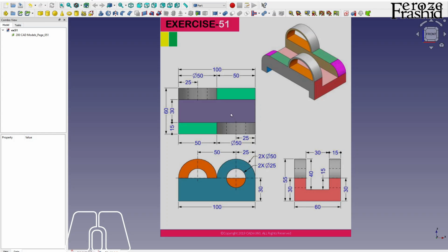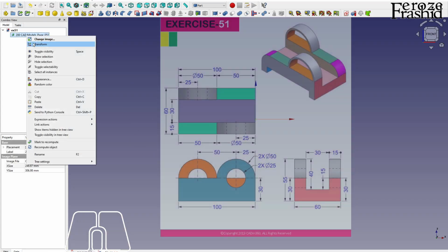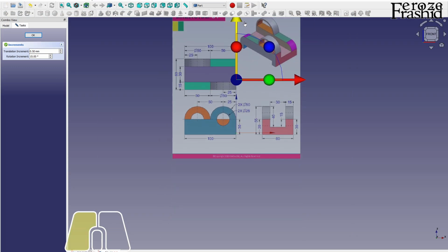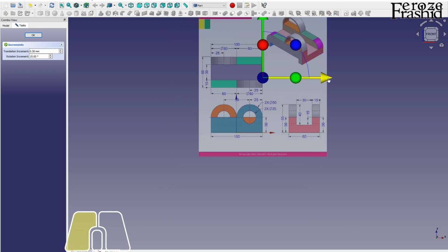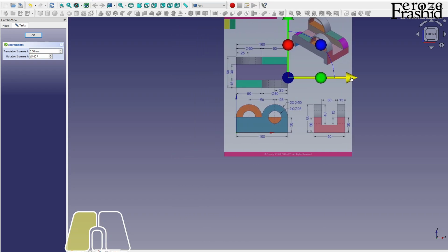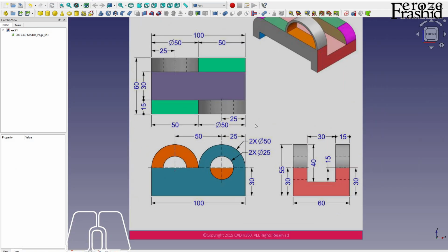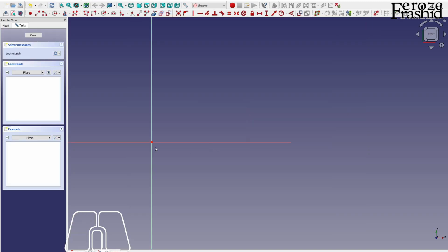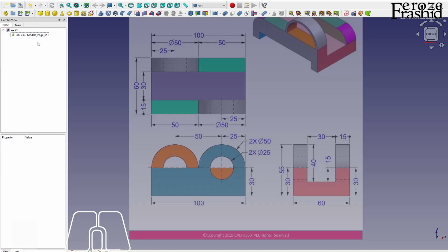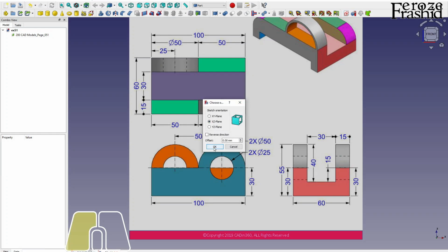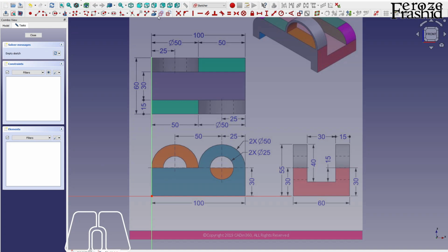What I'm gonna do is use this top view, front view, and side view to build the 3D object. So let's not focus on this object at all. With that, I am going to relocate my image to match with the center of the object, which is at one of the corners that I want to start with. Let me take that axis cross away and start building my sketch on XY plane. I'm sorry, I'll be building this sketch on XZ plane. That's where the image is at.